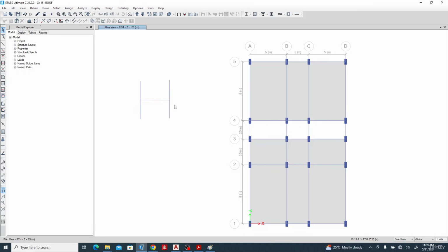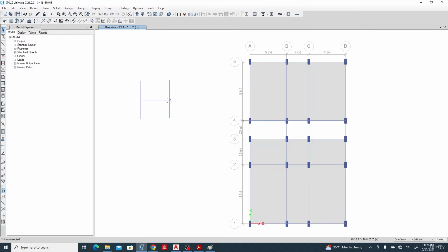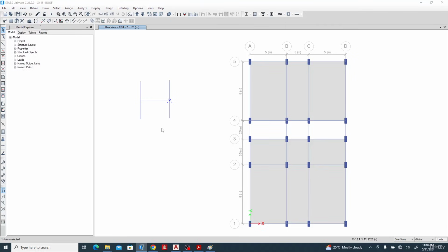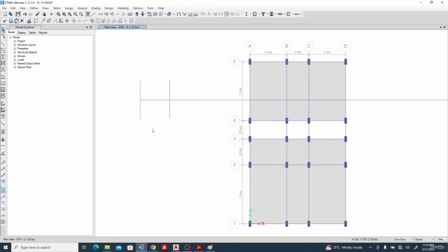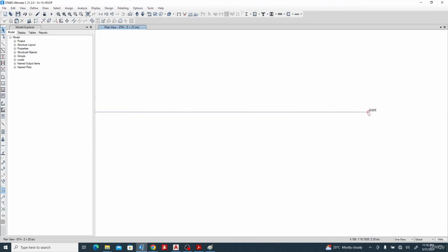Another thing I can do again is to select that joint, go to edit. So in the x direction I can put any value I want. Let's say I want it to be 125 or so, or 156. So you can see it has moved to that coordinate, 156. So you can look at it now. If I put my mouse here, look down on this point, you'll see the coordinate. So you can use all this to tamper with it.